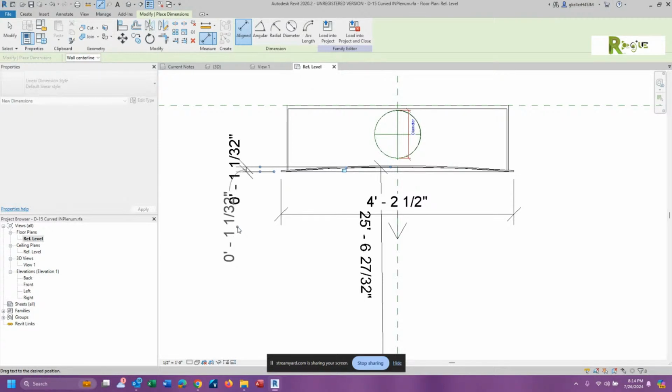About like that. There's actually a sweet spot where you want to snap. I was trying to show Tyler that the other night. Did you just feel it right there? You see how that's the elevation you're supposed to put it at. Usually we like to put that a little bit closer, but that's 100% up to the user or up to the person who's stamping the drawing. That's our rise. You got the chord length, so you need the angle. In order to dimension to the angle, we got to go back to the annotate line.